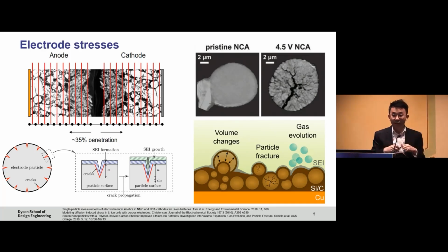It's a little bit less in the cathode, but the problem with the cathode is that the Young's modulus is very high, so it's a very stiff material. It behaves like a ceramic-like material. And that can lead to cracking of the material, which accelerates SEI layer growth as you have more surface area and a whole range of other properties as well. So we want to understand this.